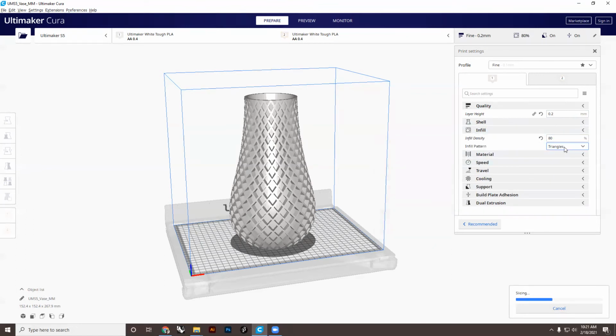Within the infill density, you also have options on how it's infilling. This might have a little bit of an effect on the structural performance of the project. For most of these types of prints that we're doing with PLA, it's not going to have a huge impact, but if you know something is going to be compressed in one direction, you might want to use a grid that's going in the counter direction, or you might want to triangulate it. There's a lot of different options that you can do.